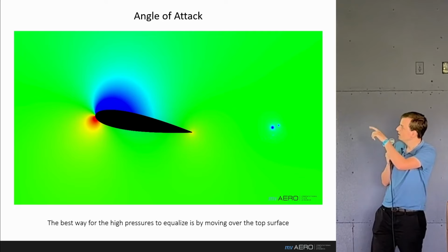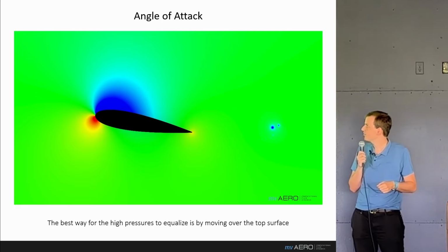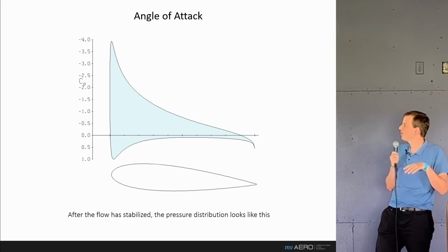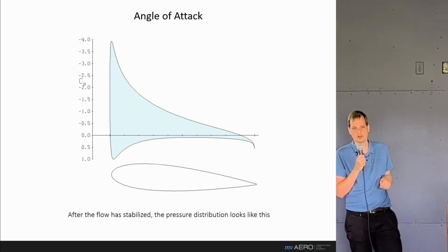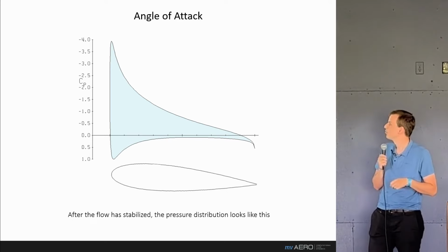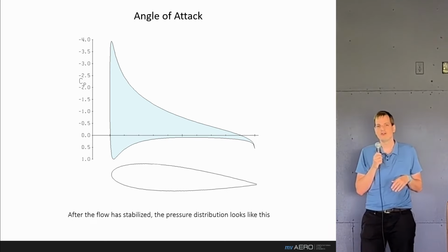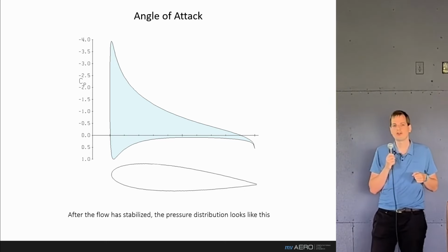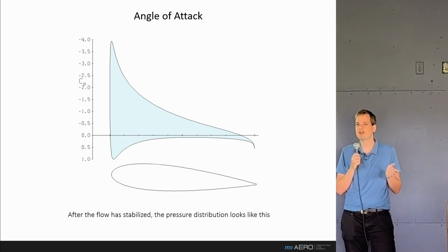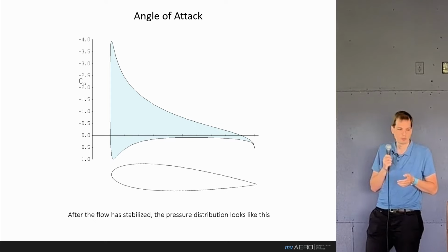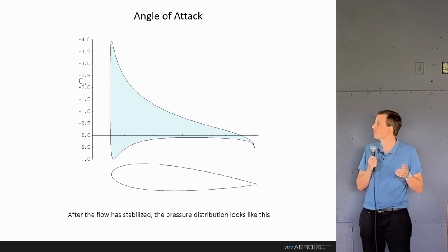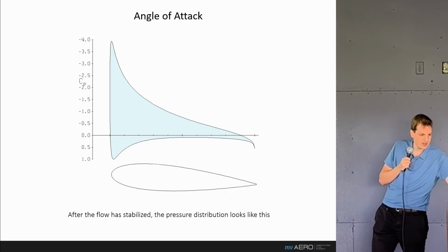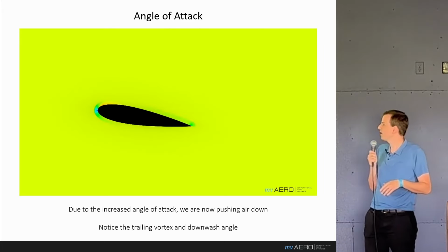With very high speeds, in blue is pressure now, but those are very high local velocities. If we then plot exactly what we just saw, but just on the surface of the airfoil, we immediately notice an asymmetry in the pressure distribution on the top and bottom surface. That means we're now generating lift. In flow, as you can see, the pressure peak is pretty high, a negative pressure peak. The flow is moving quite fast. And we see that in the simulation also.